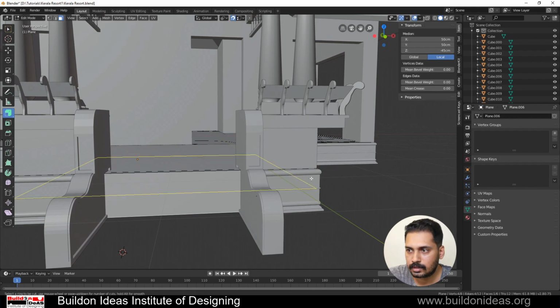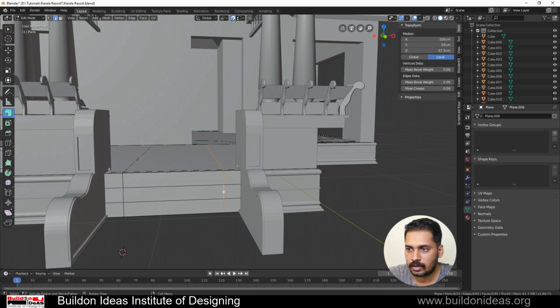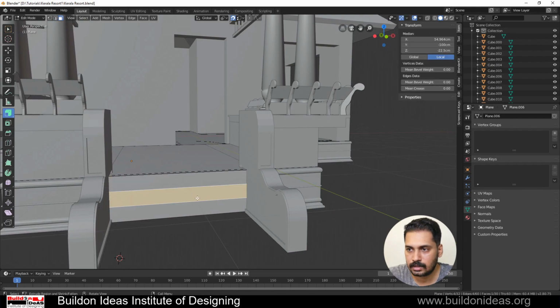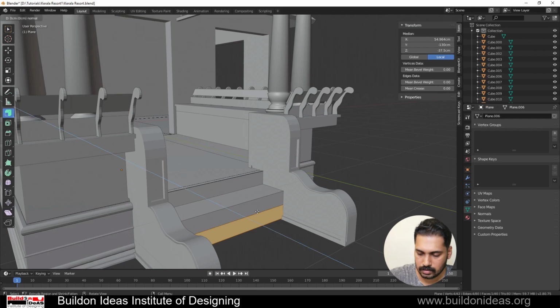In this direction I have 2 clicks, and then in this direction as well I have 2, and then I'll select all these and move it in X direction slightly to this side. Here also alt click on the edge, grab it in this direction, and what I do is select all these faces, these 2 faces, extrude by -30. Again this one also extrude by -30.